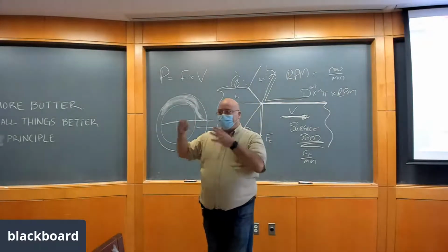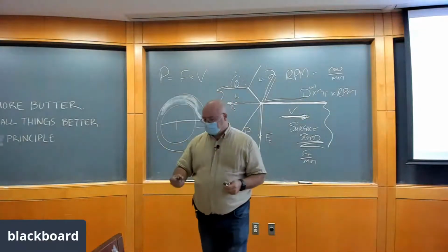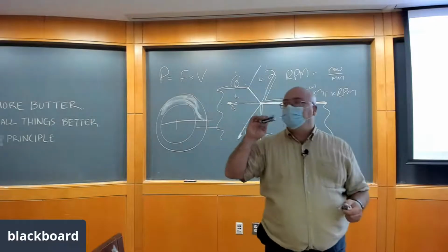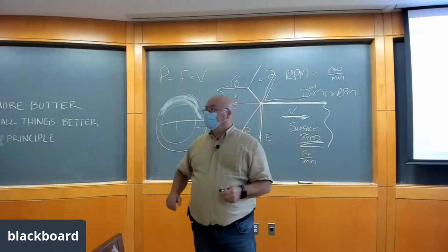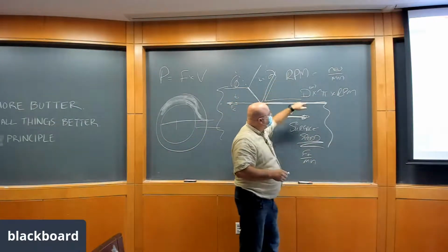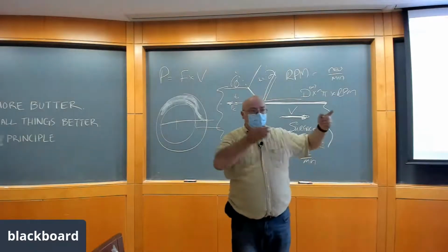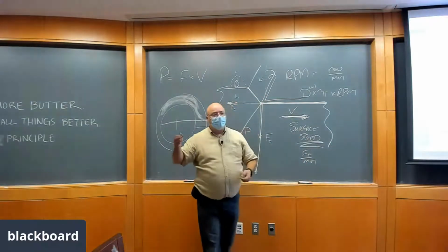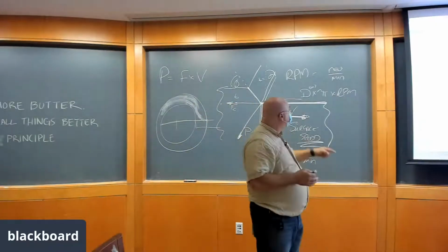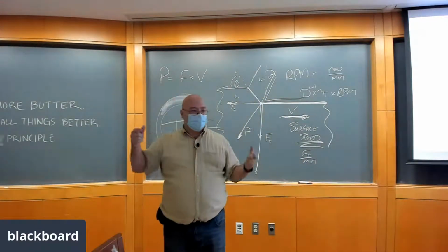is velocity a dependent or independent variable? It's a process variable. We get to choose velocity because we choose RPM. We may or may not choose diameter. The final diameter of the part is chosen by the designer, not the manufacturing engineer. We get to choose how many steps we take to get to the final diameter, though. So along the way, we choose what the diameter is. Or if it's a milling operation and we're choosing the tool, we choose the diameter every time.